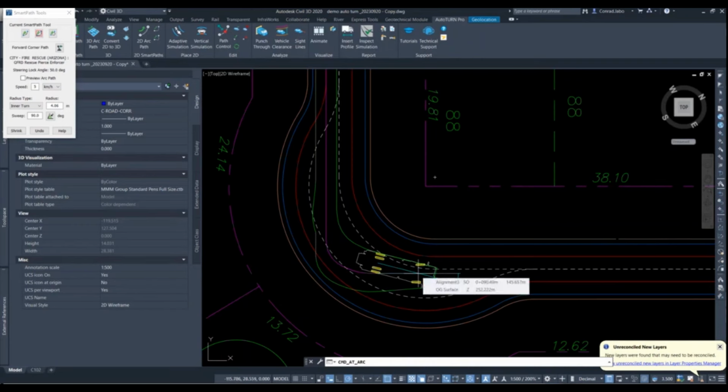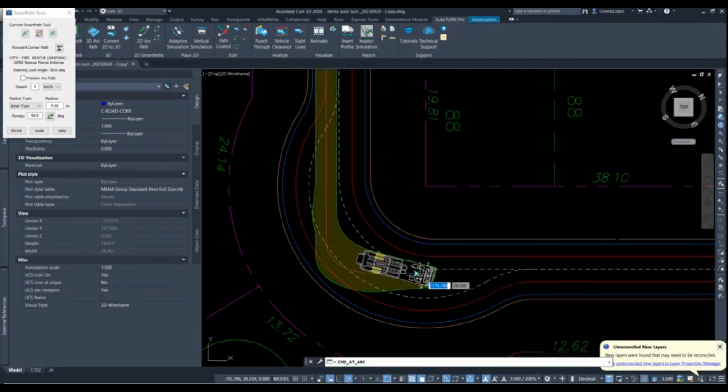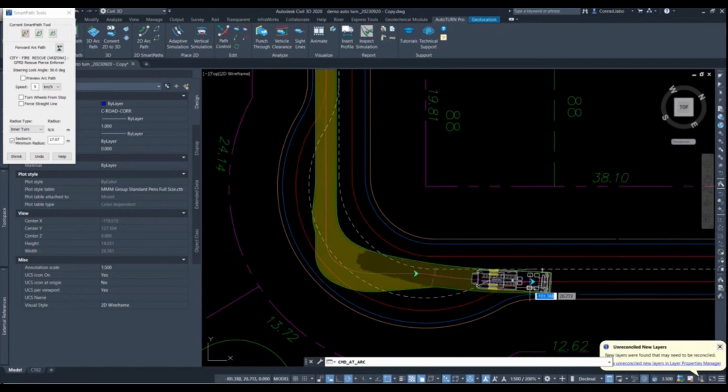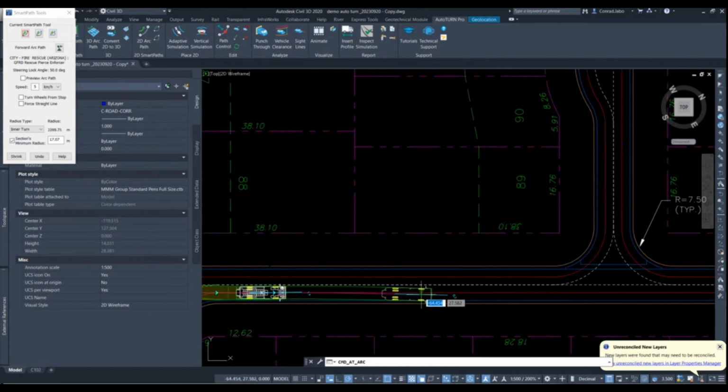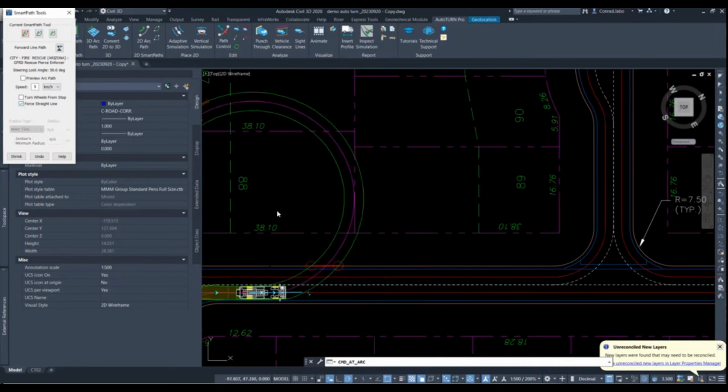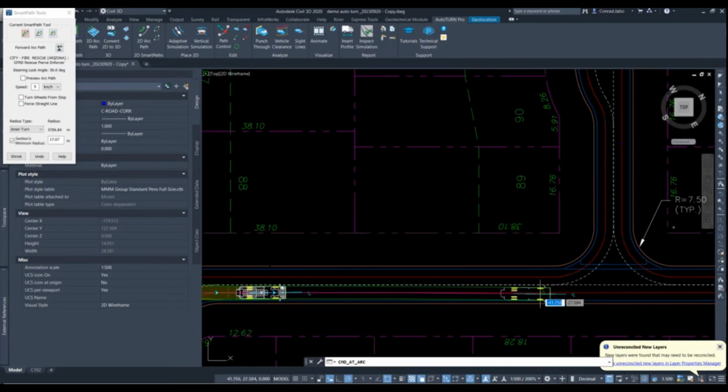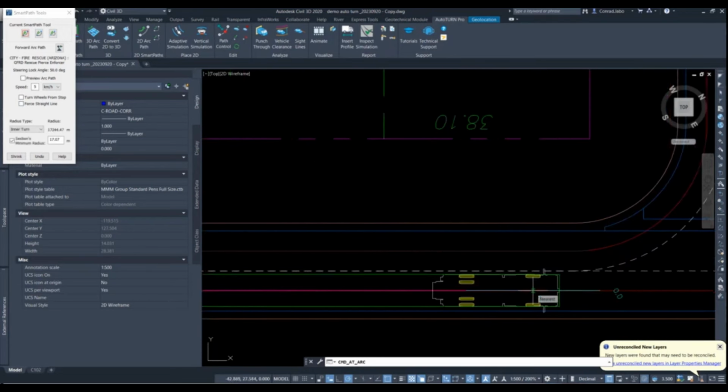So in this case, you're making the turn. So we're good. We have the generate corner path tool there. So we're making our turn, and you're switching to the normal, and then you're returning to the lane. And just like that, you're left clicking every time you have it centered. Now we could use the force straight line, and now it's going to go for straight line. So this is going into the other lane. You don't want that, and you want to keep using the generate. You don't want the force straight.